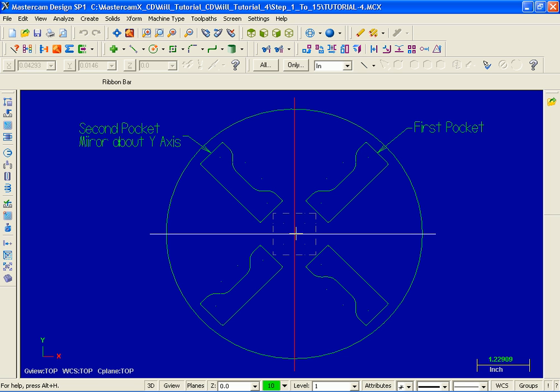Shortly I will create a new file and start at step 1. To start off, I will create the geometry of the pocket in the top right hand sector. I will then mirror the first pocket about the y-axis and then use rotate to complete the bottom two pockets. Let's get going and start a new part and start at step 1.